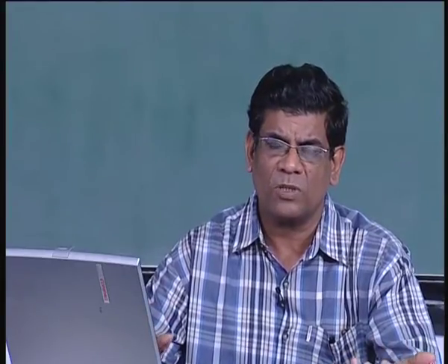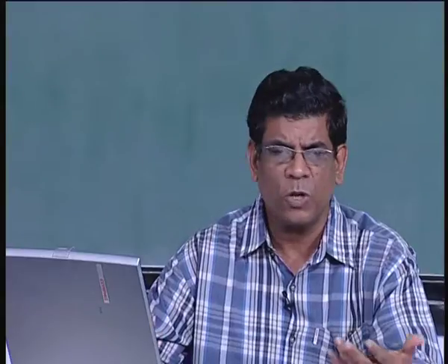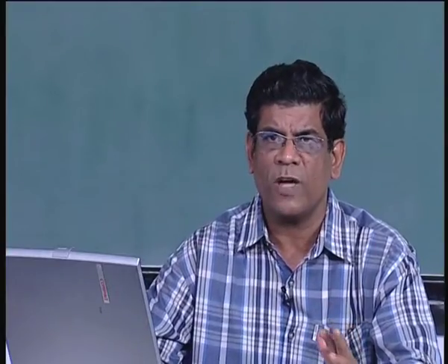Depending upon Vz, let us say plus 5 volts is the breakdown voltage of the Zener, you will get plus 5 to minus 5 excursion instead of plus Vsat to minus Vsat, which in the usual case will be plus 12 to minus 12 or plus 15 to minus 12. So, you can modify the output swing to any value you want, either plus 5 to minus 5 or 0 to plus 5 and things like that, and thereby you can have a simple square wave built around a comparator.